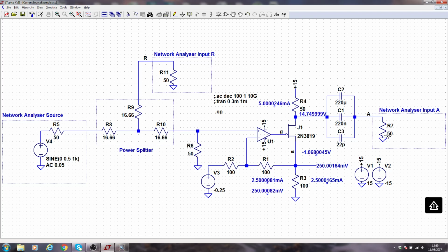It's only interested in signals because it's meant to measure linear time invariant systems only. So we're expecting AC signals going in, and AC signals coming out. As it is, we will have AC signals going in and AC and DC coming out. While I'm a big fan of Australian rock bands, it's better if we block the DC.